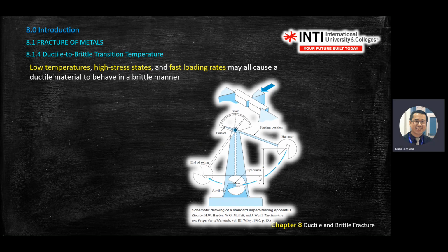If you lower the temperature, give it very high stress, and load it very fast, then you can change ductile fracture into brittle fracture.